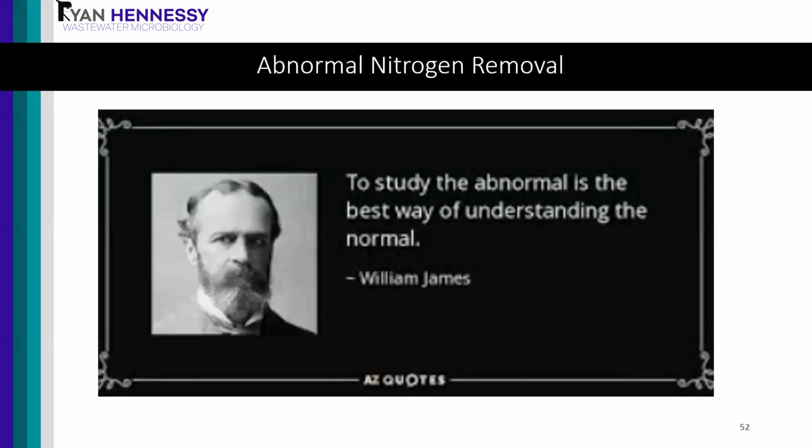So there's a good test I like to recommend that Dr. Richard invented, called the paddle test. If you have nitrogen gas that's entrapped in the flocs, you do two settleometers side by side, one with your normal mixing and one that you mix for 2 to 3 minutes really vigorously to drive out any gas.